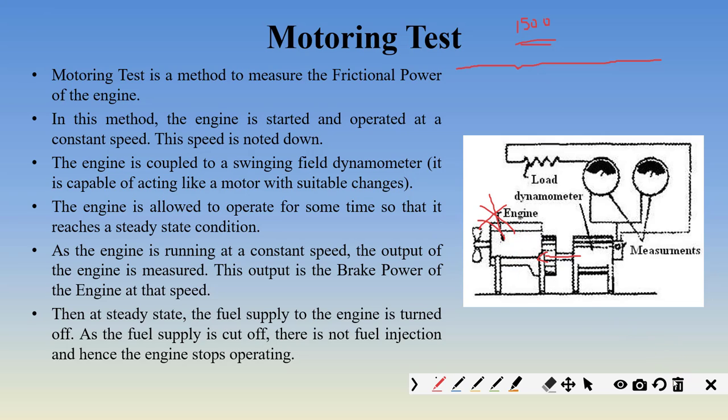Inside the engine there is no combustion, which means there is no indicated power being developed. What is the only force against which this motor is rotating the engine? What is the resistive force on the motor? What I mean to say is, this motor has to work against what force? That is the frictional force inside the engine. So by measuring the power absorbed by this motor,